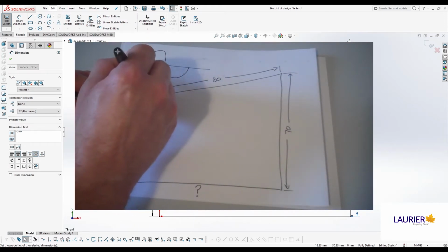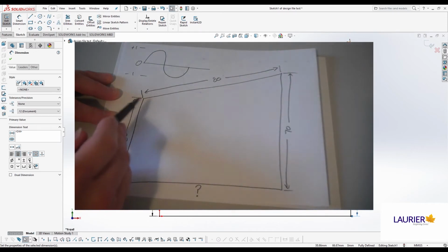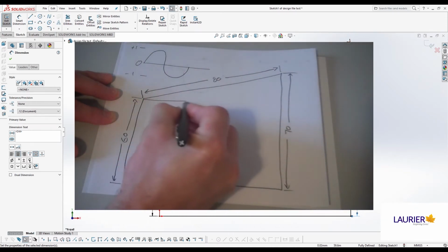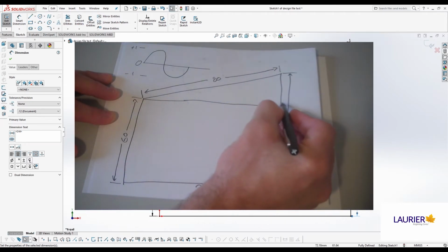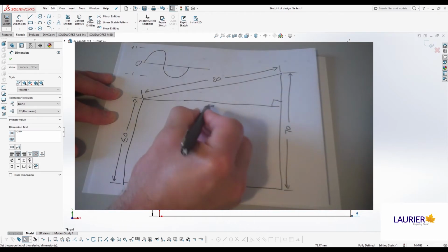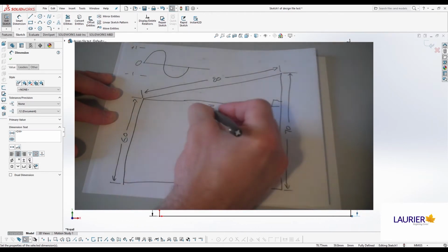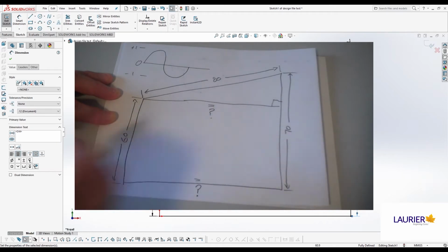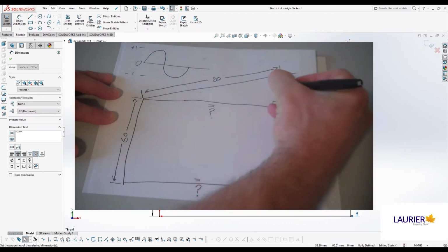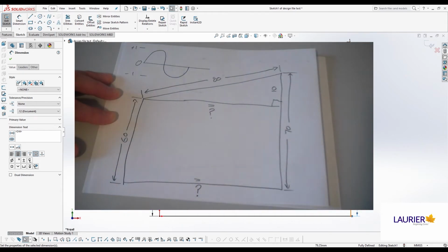So now we can take that top line and leave it at our nice angle of 70, 80, 60. If we draw a horizontal from the top of the 60 millimeter line across till it meets the 70 millimeter line, it's going to be parallel to the bottom line, which means we're back to our parallelogram. So it'll be the same length, but it's going to meet the 70 millimeter line at 90 degrees. So we've got a 90-degree triangle that has a hypotenuse of 80, an unknown base, and a height of 70 minus 60. So we think about our old cliches of SOHCAHTOA, and we can use those.